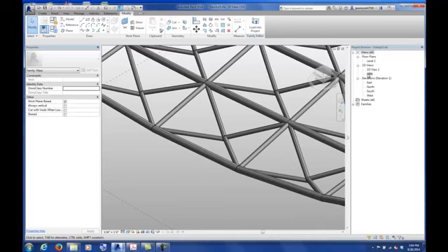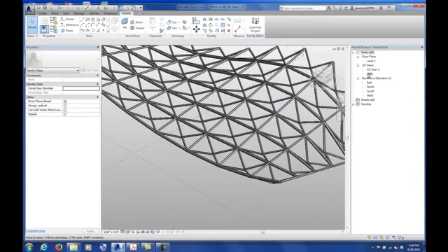Okay, I don't know if anyone noticed, but at least on mine, when you look at the screen, you see how the pipe scaled up, and it looks a little bit more realistic per the size that it's at. Some of you have said it didn't really change on mine. It depends on what your overall scale was of your grid. If you don't like the way it's scaled, all you have to do is go back and change that formula. Right now I had pipe length times, I ended up with like 0.03 or something. If you want it bigger, then you just say 0.06 or whatever. You just keep making the number bigger until you get a happy scale that you want to work with.